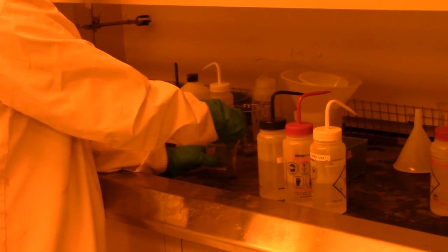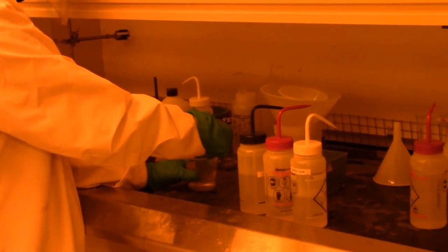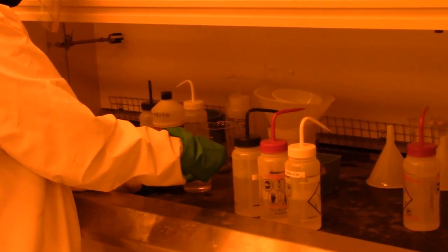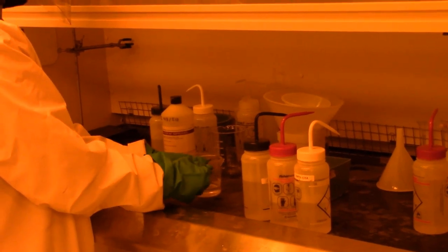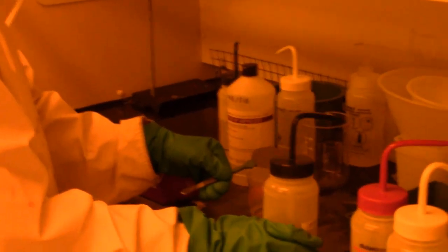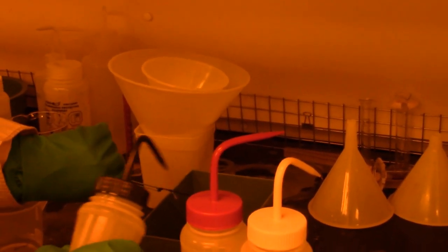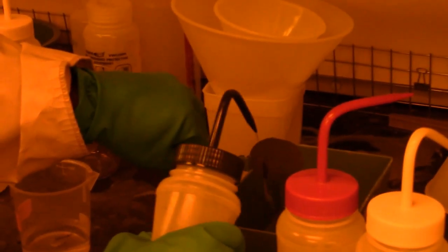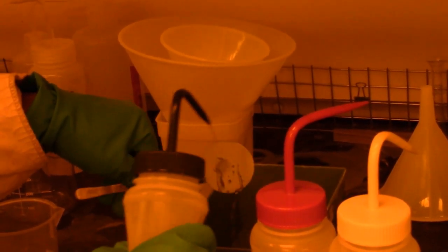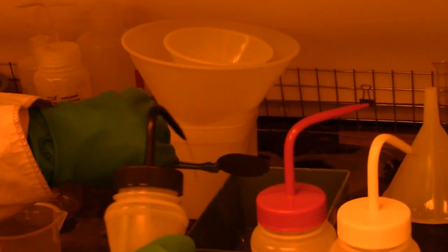Carefully, make sure to not have any splash. It is important to not over etch the wafer as well, so you don't end up losing a lot of oxide on the front side of the wafer. Once you take the wafer out, immediately clean the wafer with well water, both front and back. It is important to clean any surfaces that might have been exposed to hydrofluoric acid thoroughly with well water. This is to make sure that you don't get any hydrofluoric acid onto your gloves later on once you take the wafer out.